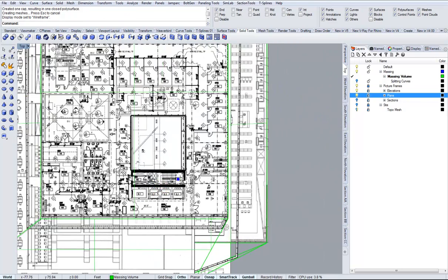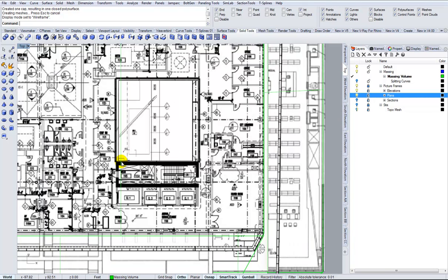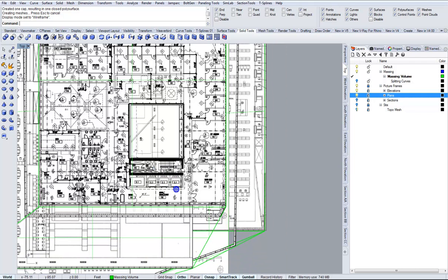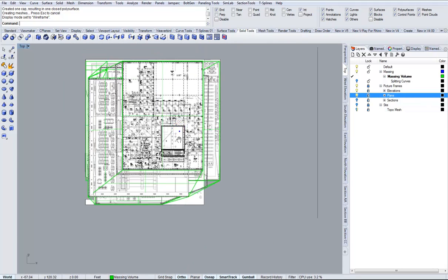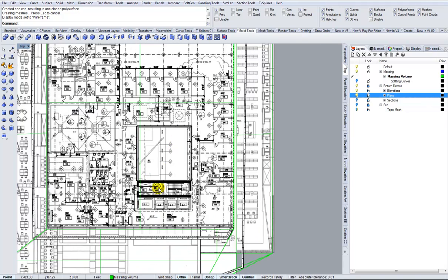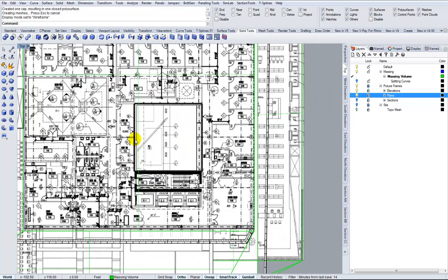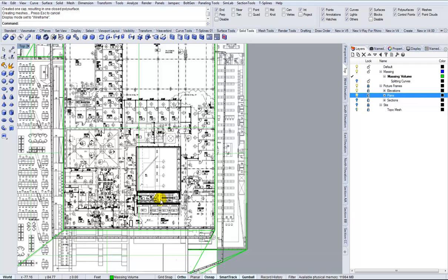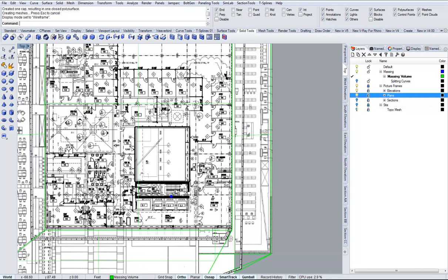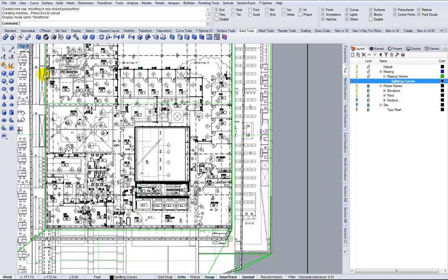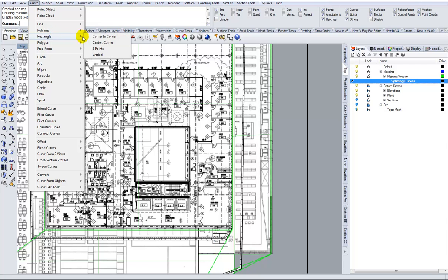And in my top plan, you can see the stair and elevator access for the roof, and this is where we're going to create that volume on the top. Since I want to split the face right in the middle, and it's just going to be this rectangle, I'm just going to draw it. Just like any other split command, if I'm in a parallel view, I don't even have to worry about where my world C plane is, because I can just draw it and split the face with a curve, and if it looks like it's on that surface, then it's good enough to split that face. So I'll turn on my splitting curves layer and just do a rectangle.